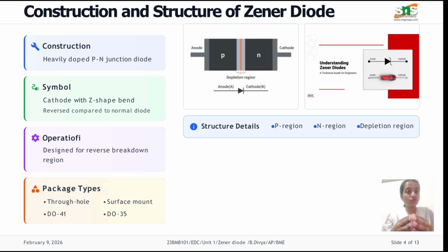How does the depletion region form? When the anode is connected to a positive terminal and the cathode is connected to a negative terminal, and the supply voltage gets increased, the holes in the p-type and the electrons in the n-type recombine, or are attracted together, and form a layer in between the p and n-type layers called a depletion region.